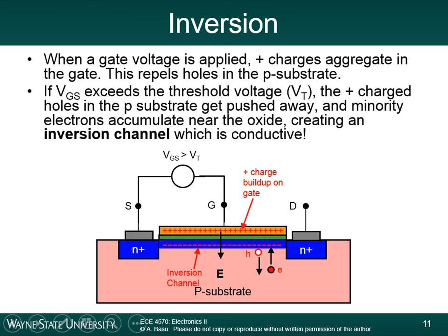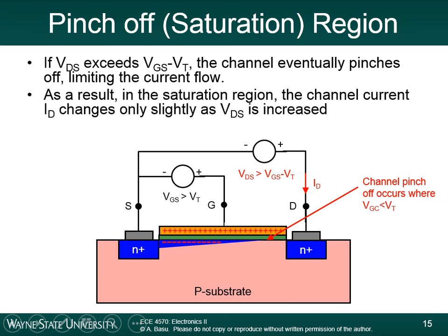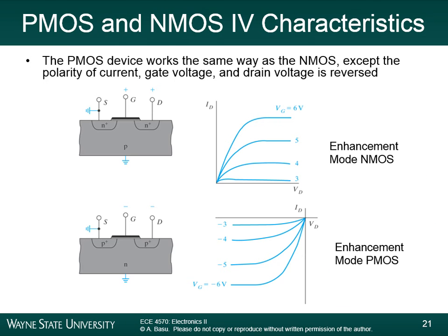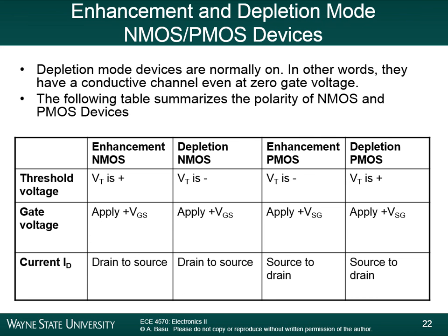The answer is actually a little bit more complicated than that, because it'll make more sense when we start talking about threshold voltage calculations. The threshold voltage depends on a lot of factors. It depends on the metal to semiconductor work function. It also depends on the substrate doping levels. It also depends on the depletion charge. So by tuning some of those parameters, you can actually get negative threshold voltages. But there is a step called ion implantation, which actually implants a certain amount of charge in the channel region. So it is possible to have negative threshold voltages.